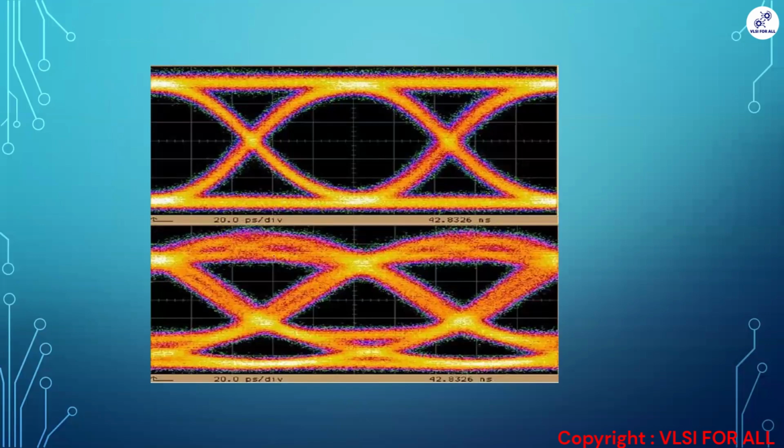Can anyone tell which eye diagram, the upper eye diagram or the lower diagram, is a good eye diagram? Like the sampling and less error, less jitter, less ISI. Upper eye diagram. Yes, the upper eye diagram is good because the eye size is big. We can see a wide opening, and we are not seeing any signal overlapping here.